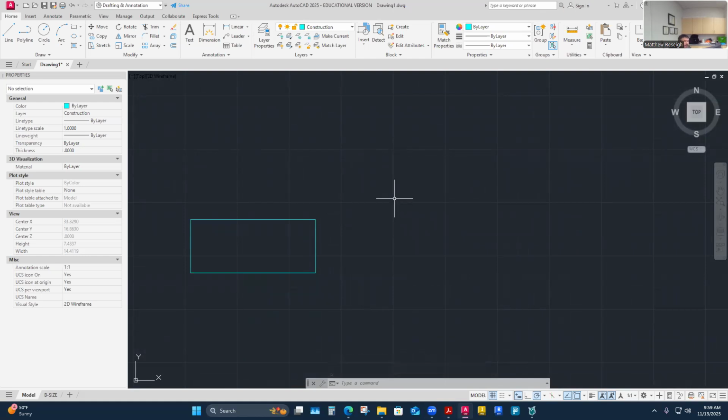So I'm going to kind of break away from this. When I draw this type of perspective, I don't really need the ISO planes turned on, because I'm not at a 30-degree angle or a 60 or anything that's going to be parallel or perpendicular to this grid plane. I'm actually going to be at a 45-degree angle projected back, and I'm going to do that with my 45 tracking on here. I've got that tracking. So at 45 is going to be my perspective away from me like this, right?